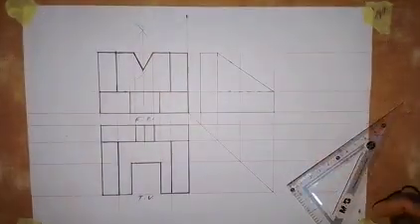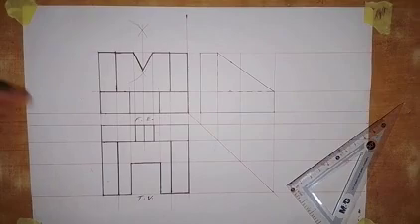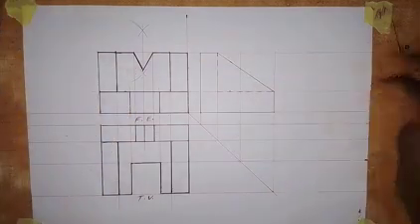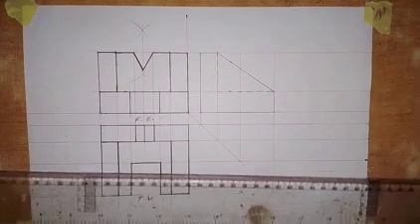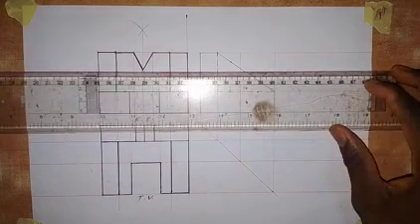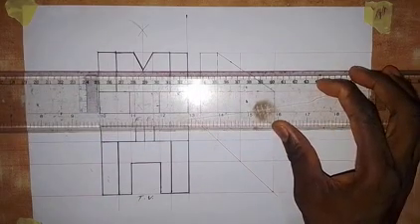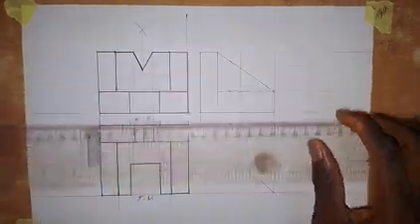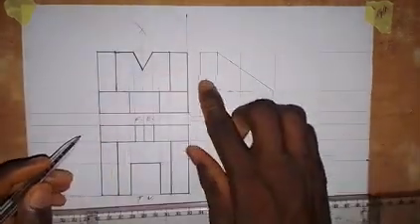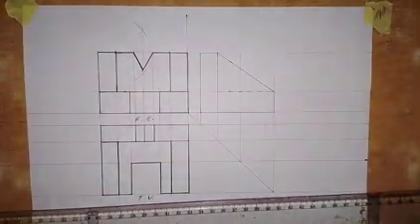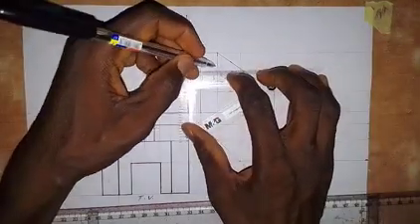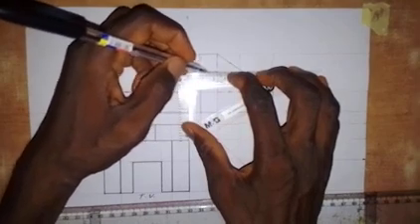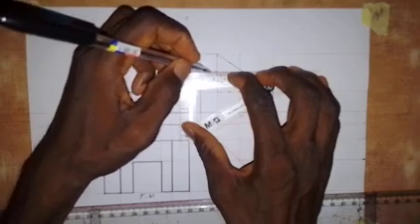Another thing that we have to have here is that there is a line at this point that we need to show here as a hidden line, based on the direction of view of the end elevation. So from this point we draw a horizontal line, and it goes like this, within this part. We also draw it as a short dashes line. So this is how it should be.